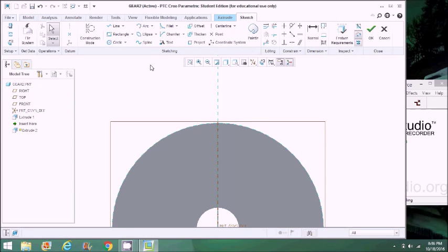Now we're going to use this line tool up here, if you can see my mouse, and we're going to be making the teeth. We will use 4 different lines and 1 arc to complete this. First you're just going to create 4 lines. You can see here that once you get the L over both line segments on the top, that means they are equal length, which is what we'd like to see. Then you can just finish this off.